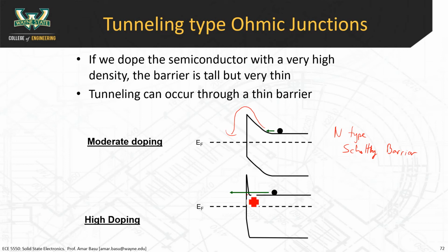In this little region here there's an absence of energy states, but because that region is so small, the electron can go right through it. This is sometimes called punch-through tunneling. They say the electron punches through the barrier, and the reason is you can think that if you have a thick concrete wall versus something as thin as paper, it's obviously easier to punch through paper, right? That's why they refer to it as punch through. They're trying to build up an intuition there.